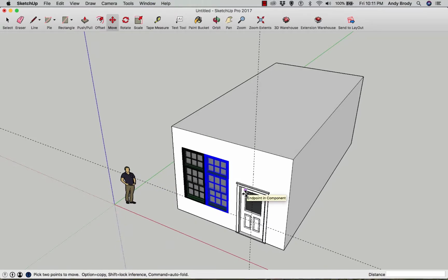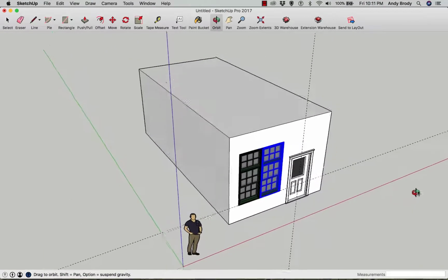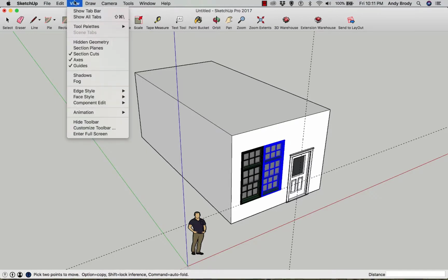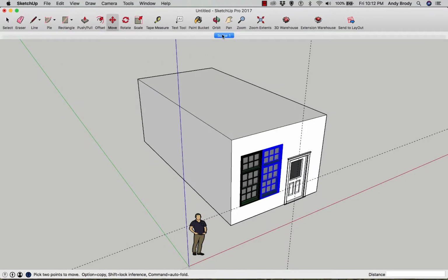Now, one thing that I did not mention in the book, I sort of jump in, I believe it's page 83, into the description of how to add the wall thickness to this lovely existing conditions. But I mentioned saving a scene, but I didn't actually say how to do that. And it's under the View pull-down menu, under the Animation grouping. There's an Add a Scene section. So that's how you do it. And you can right-click on it and rename it and call it Overview if you so desire.